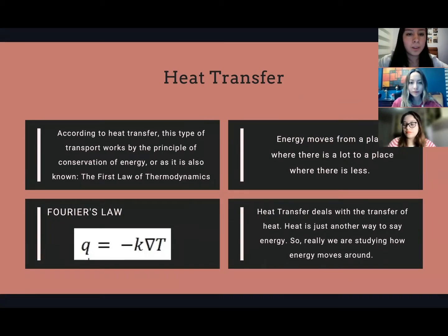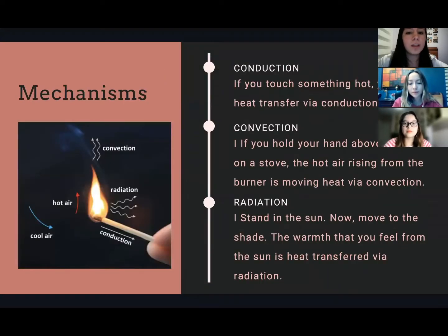First, it is very important to identify the mechanisms in which energy might be transferred from or to the control volume. After this, energy can be quantified. The object of study will have two types of energy. The first one is internal energy, also known as thermal energy, which considers the vibrational, translational, and rotational motions at a molecular level. Moreover, kinetic energy is considered as well, and it is related to the macroscopic motion of the object of study. There are four types of mechanisms, which are convection, conduction, mechanical energy, and energy transport by subatomic particles, also known as thermal radiation.